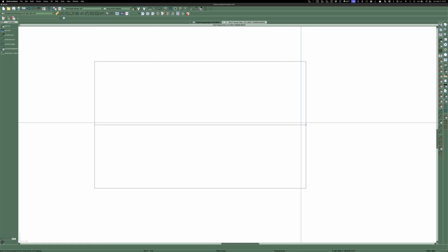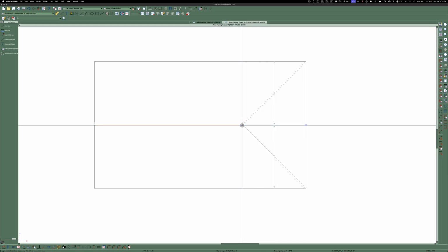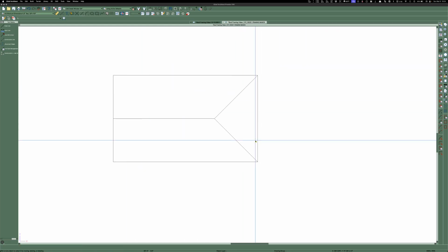So if I was going to do a line drawing, and I'm using Chief Architect right now just because, there's a line drawing, and then jacks. I'm sure he's going to go 2 feet on center because that matches trusses and stuff, but I'm older than he is, so I do 16 on center. So there's what it's going to look like: 6 and 12 on both of these sides, 6 and 12 on the end. This line really here would be like that. If you were doing a roof layout, that's what it's going to look like from the sky.